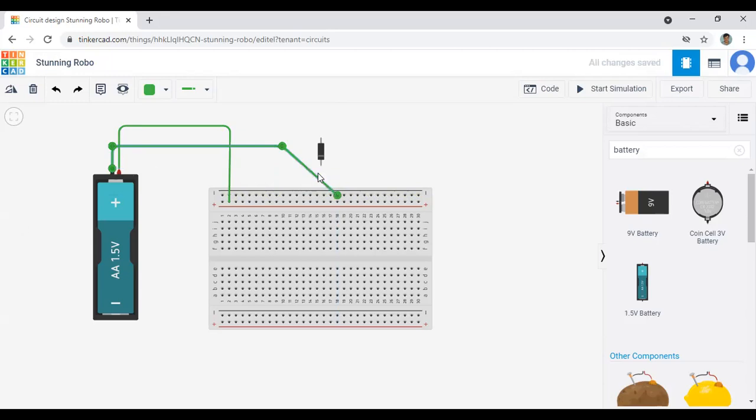Then what is happening? Because this breadboard has a connection along this line, when you connect negative here, it will go through the straight line. All these points will be negative. If you connect the negative to this point, that negative will come to all the points in this line. Is it clear? All the points in this line will be negative. And when you connect this positive, all the points in this line will be positive.